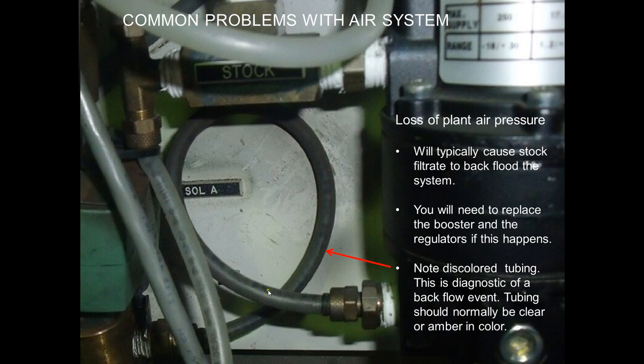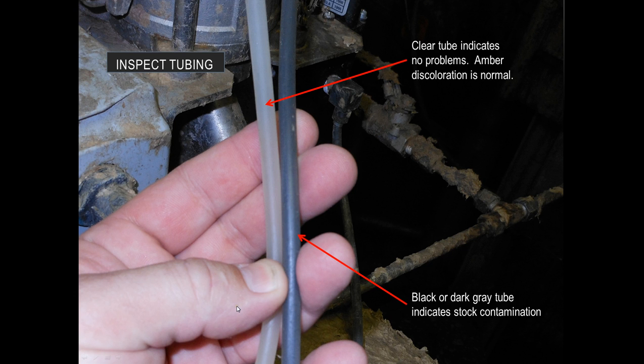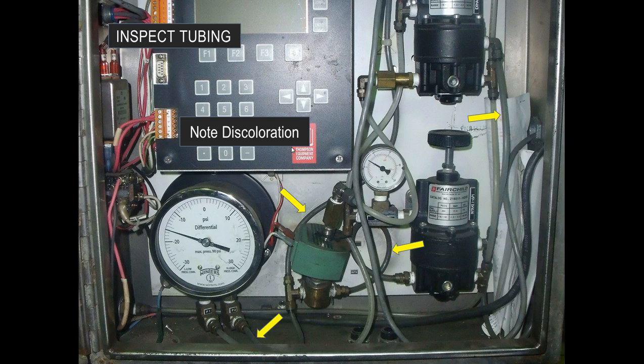This is pretty much diagnostic of a backflow event. When that happens, you've had one of them, and chances are you're going to have to start replacing a lot of pieces, like the intake regulator and the solenoid valve. This should be clear tubing, more like this little piece right here. Just to illustrate that point again, here you have nice clear tubing. Here you have tubing that has been flooded with debris. Amber discoloration of the clear tubing is normal and not a reason for any concern. Black or dark gray is indicating that you have debris inside that tubing.